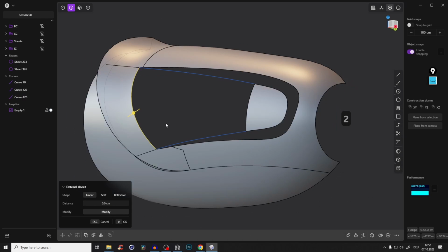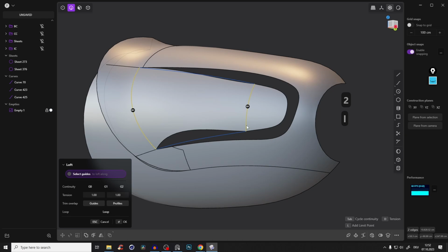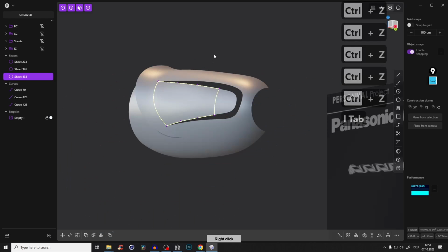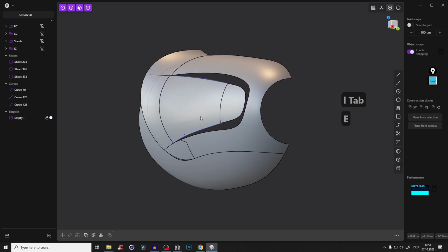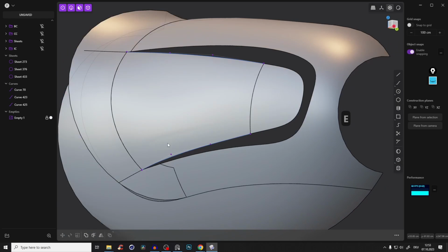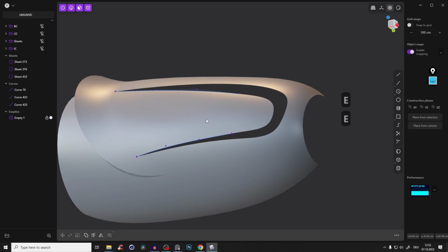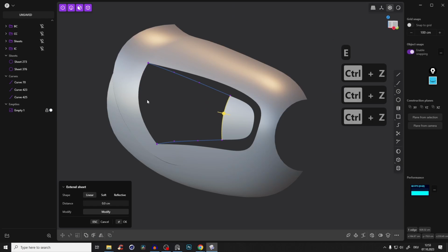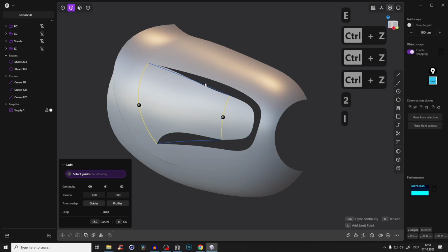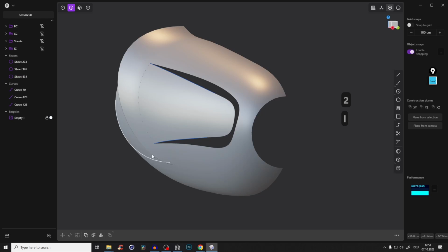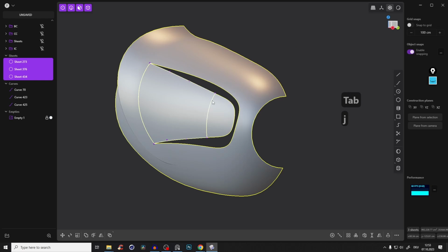So we will select this edge, loft it, Shift, tab, press OK, and voila, guys. And we see we have super tiny stretching here. So let's go back and loft that with G1. It should work here in this case too. Otherwise we have to adjust the curves, but here for now it's fine. So okay. And so with G1, join that.